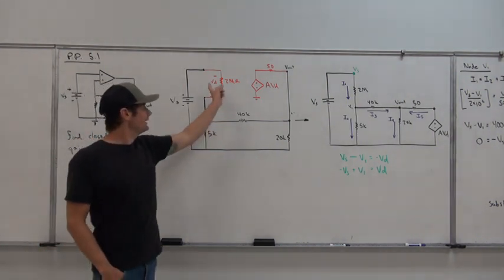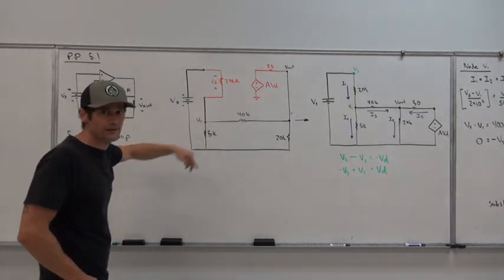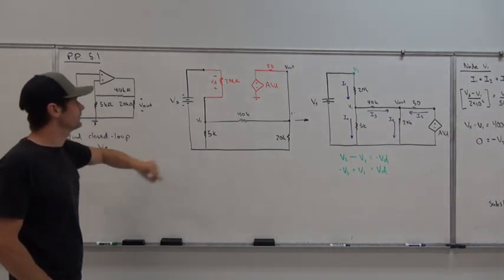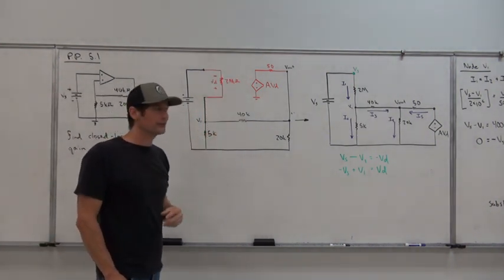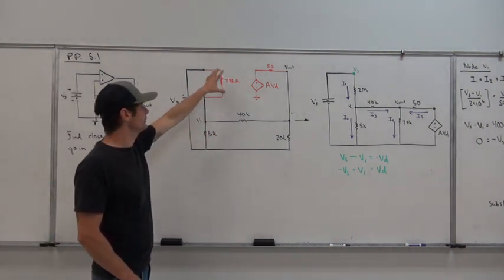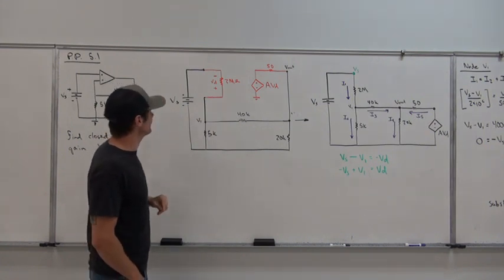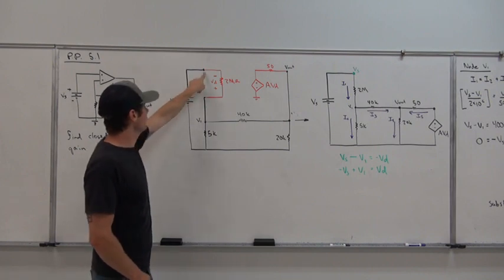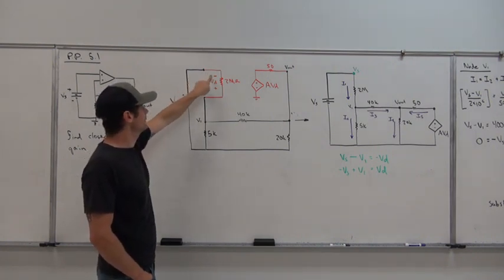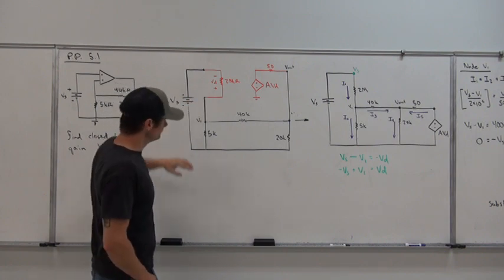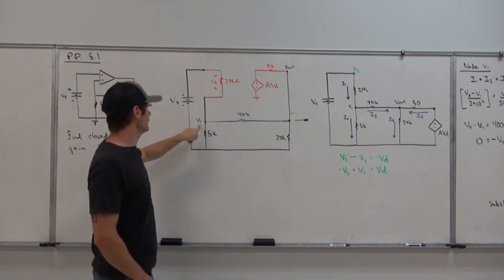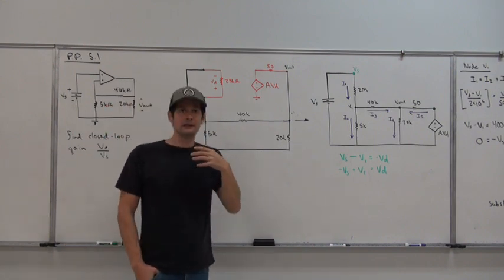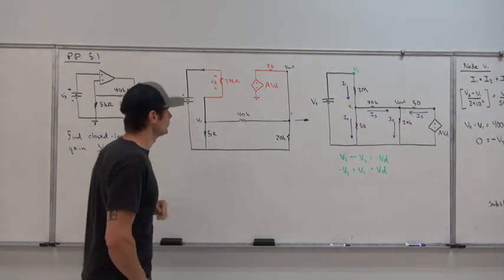One thing I want to note, because I think this may confuse students: would this internal model change based on the fact that Vs is connected to the positive terminal? Why wouldn't some things in here flip? I've heard this question before, and in terms of where everything's connected, that's not the case. What really matters is that Vs is now connected to the negative terminal of Vd. The positive terminal is tied down to a different node, and that drives the non-inverting aspect to hold true.